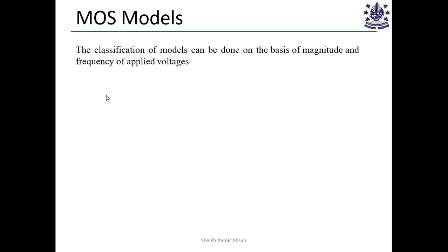So whenever you use any circuit simulator, for example, IC-CAP or Cadence or Mentor Graphics or any well-known commercial circuit simulator, and if you want to design a circuit using, let's say, a basic 180 nanometer MOSFET, you'll take a MOSFET symbol and drag it from the palette and place it in the schematic, and then you'll add your various components such as the bias sources, the resistances, the capacitances, and other elements.